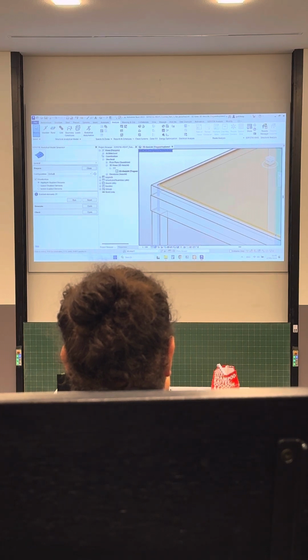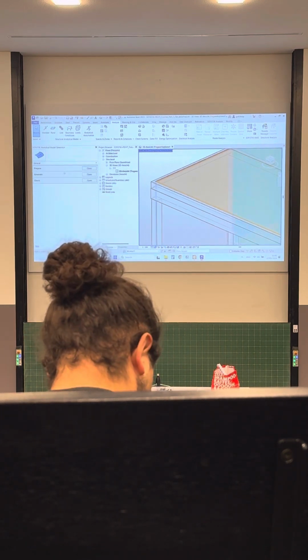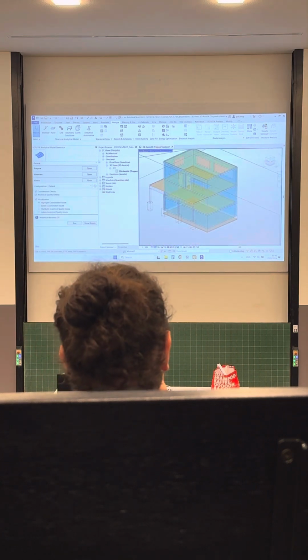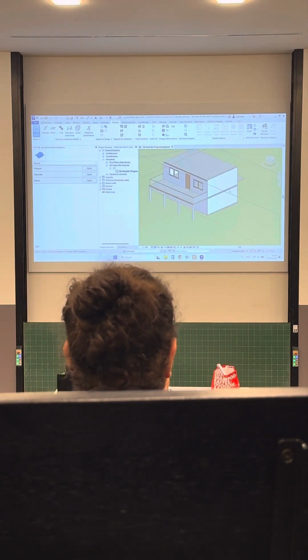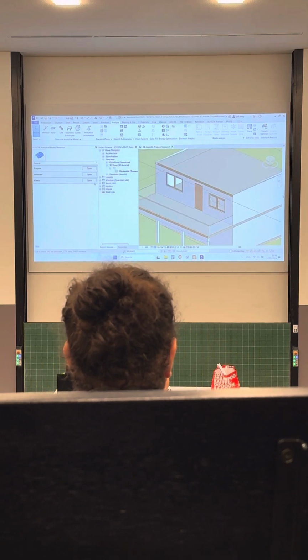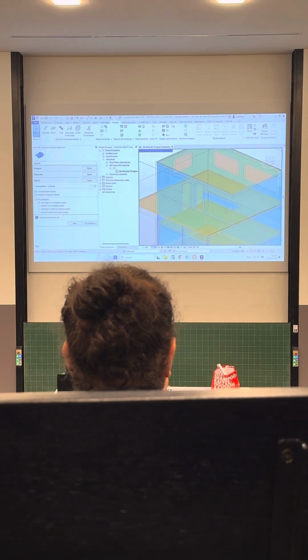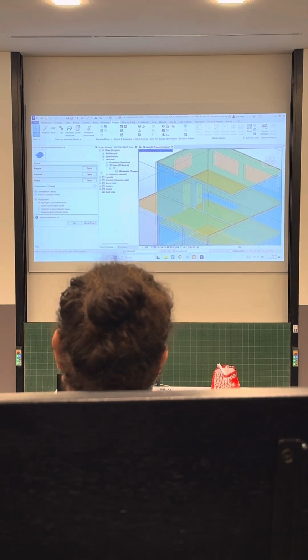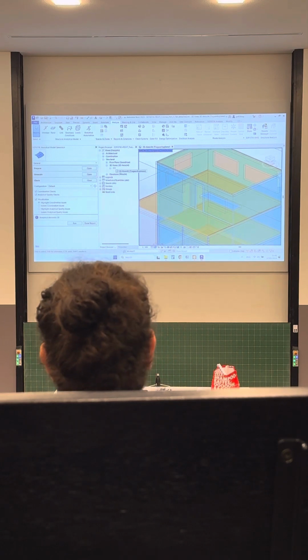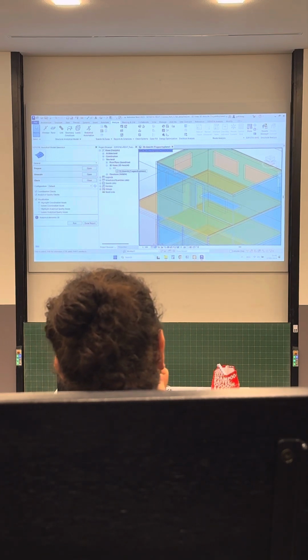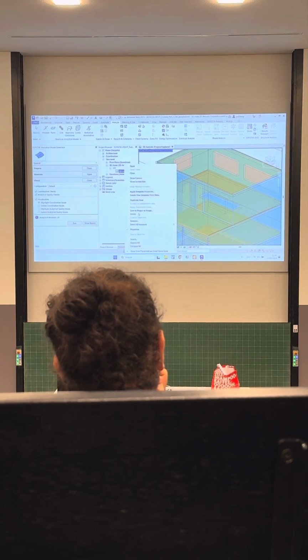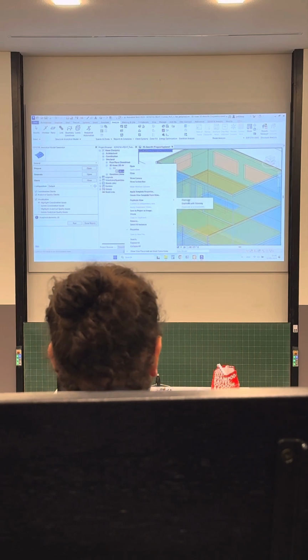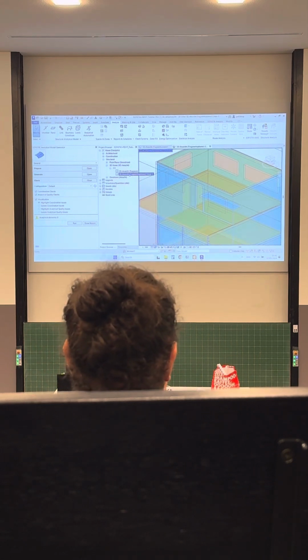And the thing is that now, after we generated the model, if we close it, it will basically disappear. And I'll show you how to create a view. Of course, you can do it also here, just after you run it, there is such a button to create a view. But we're going to have a specific view. You go to the 3D Ansicht, 3D view, and you duplicate it. Duplicate the view, and you call it 3D Analytical, for example.